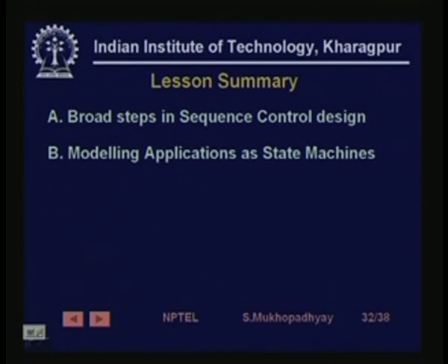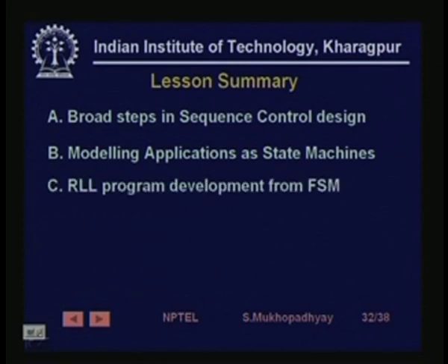We took a very simple industrial application like a stamping process and built its state machine, and then we showed how, given the state machine, very mechanically you can structure your program and then write the transition logic, the state logic and the output logic. And we have seen that this is very much expected to lead to error free programs.